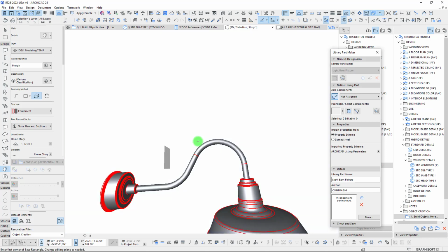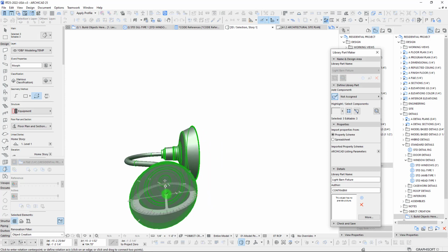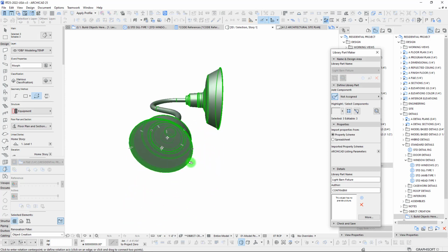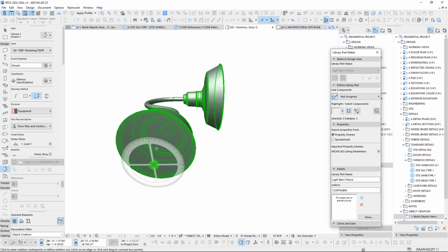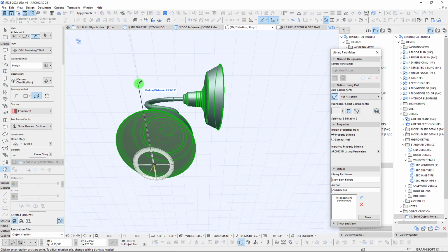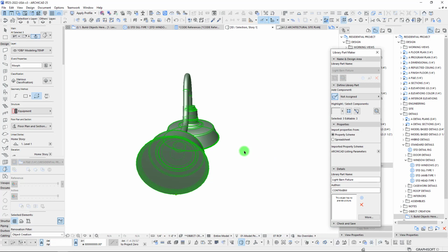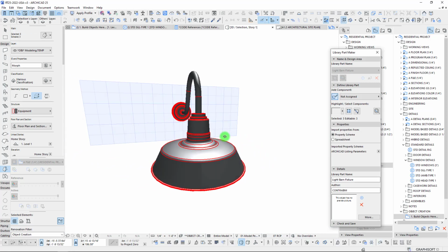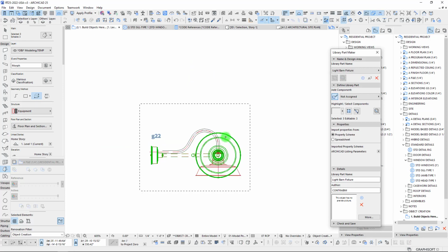But yeah, okay, from here, obviously we need to rotate this. So we are going to rotate this from our center point over on this side. We've got lots of little center points popping up, but let's find one over here. Now it doesn't really matter that much where this point is. All we need to make sure though is that we're rotating this an even 90 degrees. So, okay, there is our light fixture. That looks pretty good. And all right, so there we go.